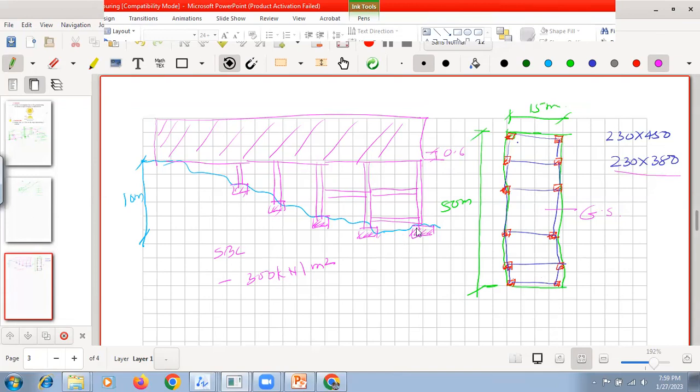Okay, but here the situation is totally different. Can we go for the retaining wall? Either you can keep this space open for the use, or around the periphery you can go for the retaining wall. So around the periphery, you have to construct the retaining wall, okay, then you have to fill inside, and then you can take the grade slab and proceed further.